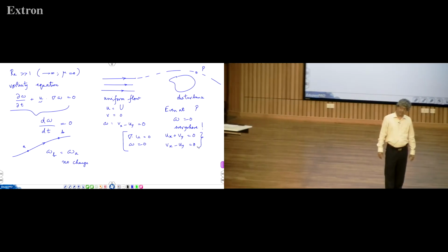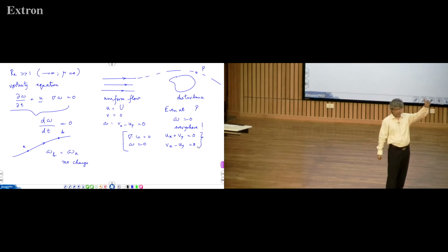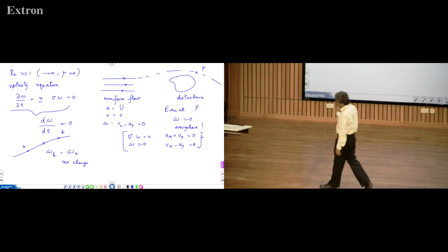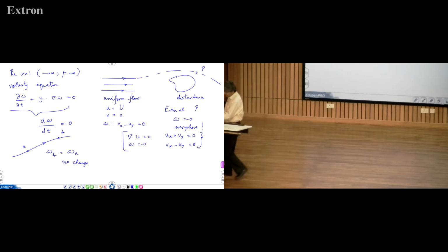So, you have succeeded in drastically simplifying the Navier-Stokes equations: take a limit Re approaching infinity, set mu equal to 0, look at the vorticity equation and replace the momentum equation by the vorticity equation. Of course, this system will hold only when the approach flow is uniform.